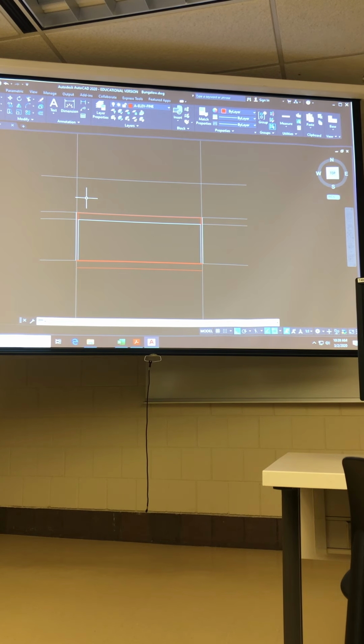Okay. Now I'm going to go ahead and just get rid of this construction line that I used to figure out where that work point is. I don't want it around anymore. It's just going to get in the way. So I'm going to start drawing now from the top of my truss, this first line that I drew at a 12-12 pitch, drawing the inside of the truss, the rest of the truss from there.